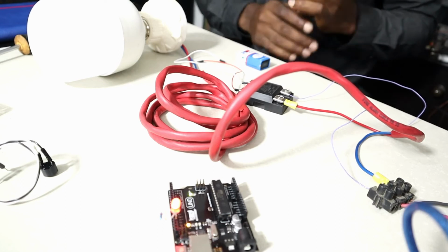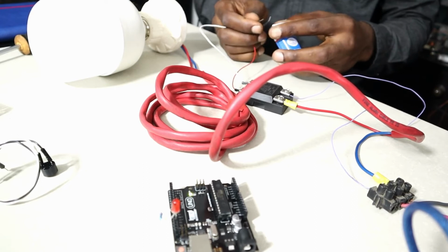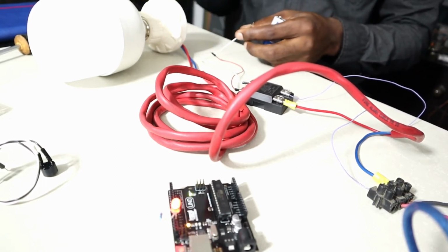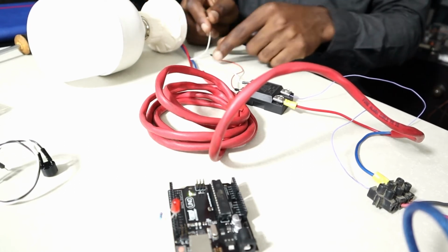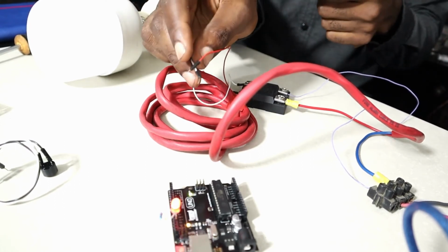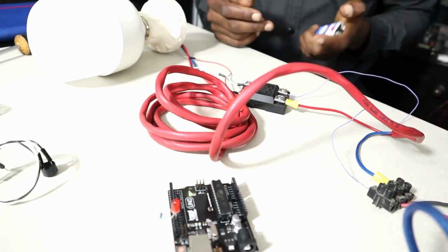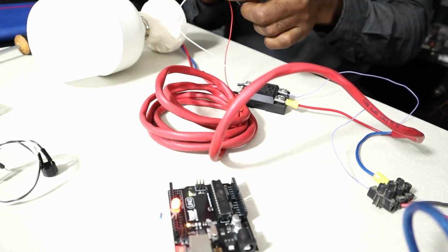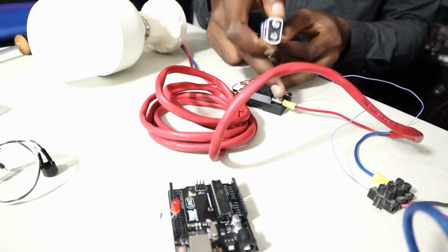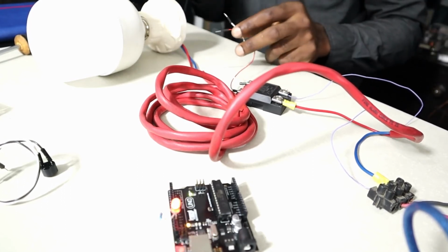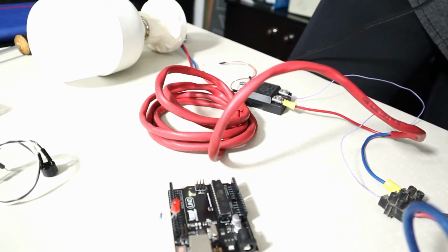So I have this. If I supply a voltage on the solid state, it will make contact from this to this, current flows from this to this, and my lamp comes on. This same voltage is what I'm going to use Arduino to supply, to show you that you can use Arduino to control a solid state relay. If you apply a voltage on this end, it makes a contact from number 1 to 2 and the lamp comes on. So let me connect so that you can see how it goes.